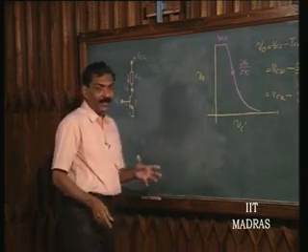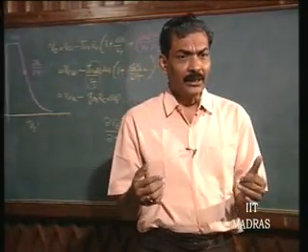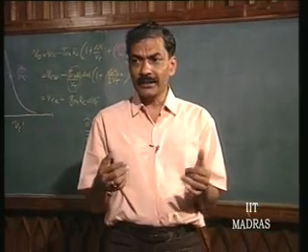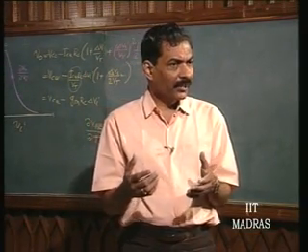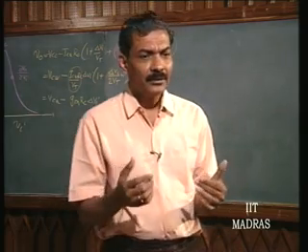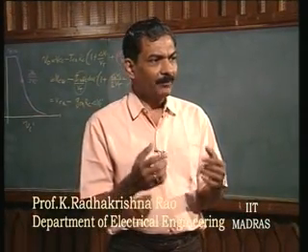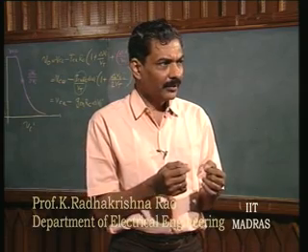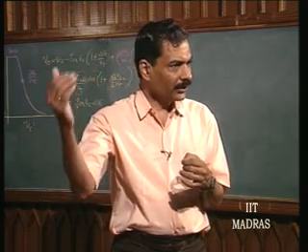And in an amplifier, when I give an input signal, I would like to give it straight to the input terminal of the amplifier. I do not want to couple it again through a capacitor, etc. So, that means preferably I would like the amplifier input voltage to be 0 when the output voltage is also 0.